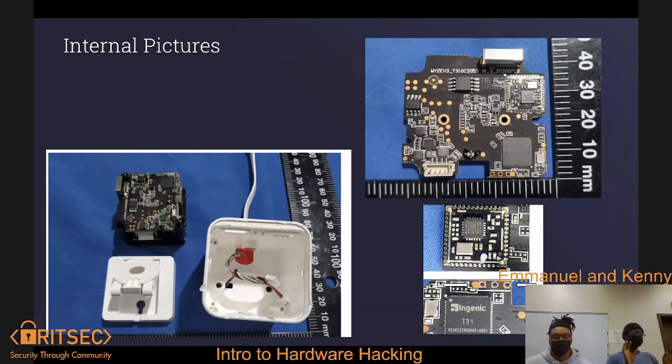So this is just the manufacturer disassembling the device themselves, so you don't have to know all this stuff. The good thing about this is you're able to see what's inside before you break it. And right there, we can see the port even before opening the device. So now I know it's there, but the problem here is it's not labeled, so I need to possibly use my own multimeter and whatever to find what each port is.